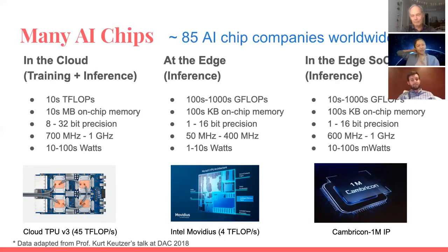However, this is not true as the transistor gets smaller and smaller. The power density will actually increase because power does not scale with size, due to the leakage currents and the threshold voltage, which has probably also been talked about in this class. This created a power wall that limits the practical processor frequency to around 4 gigahertz. Since 2006, we see very few improvements in processor frequency.